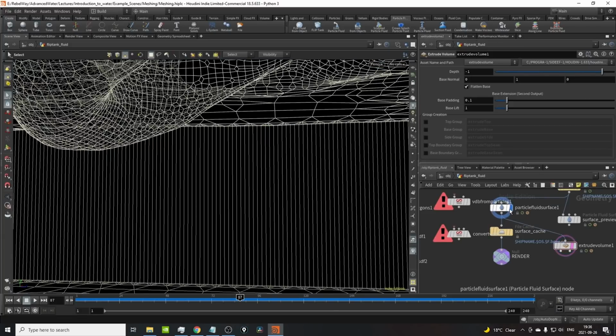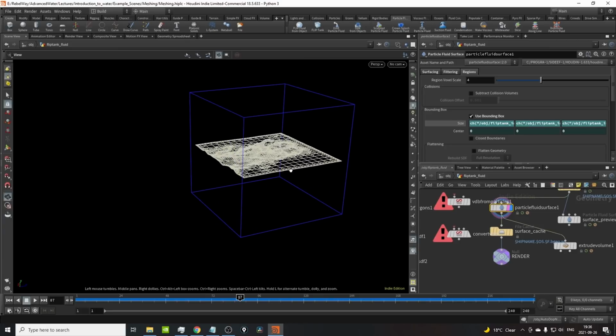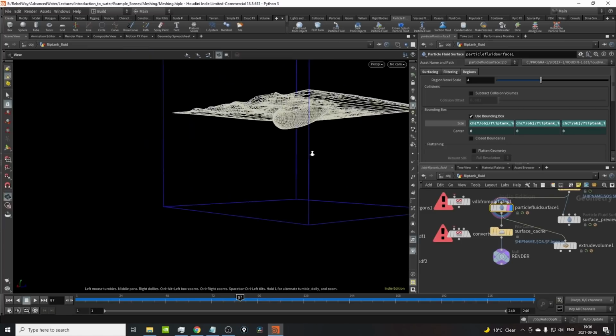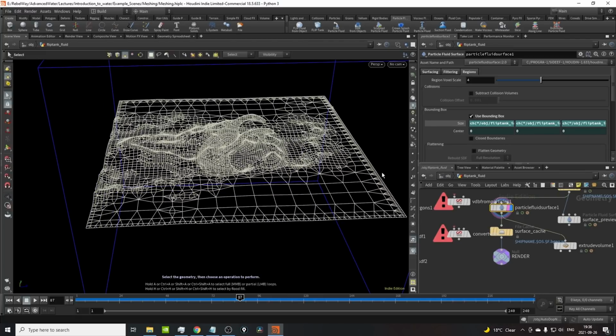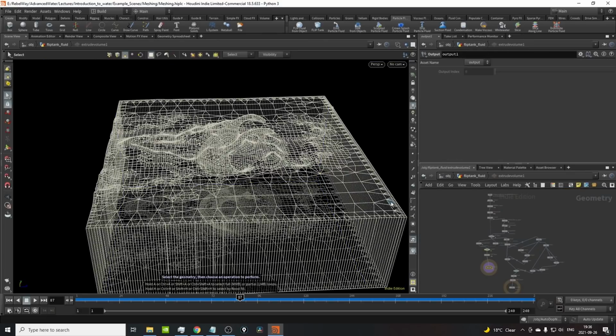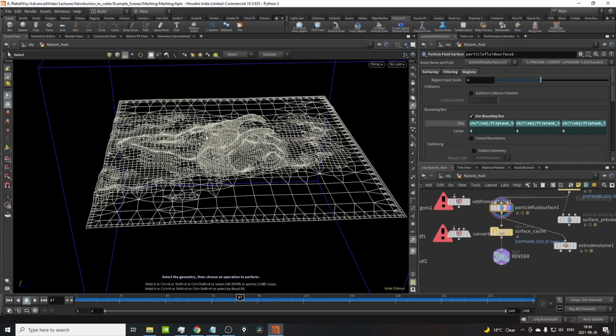But caching wise, I always cache this, just in case it's being rendered in Arnold or in V-Ray, or, you know, a camera is positioned in a way where I would see this edge. Now everything breaks, right, if I have a surface right here, because I get double refractions and all of that stuff. So I tend to play this safe and just export single surfaces like this.